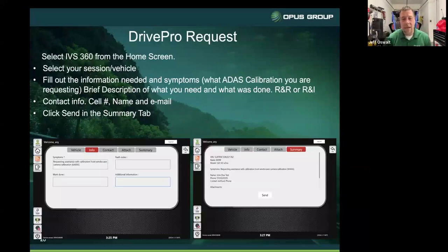If you are requesting it in the mechanical world on the Drive Pro request, now I don't use this every day, so I had to get a little help from my buddy Brandon Matthews. Many of you might know him. Select the IVS 360 on the home screen. To order this calibration, select your session and a vehicle. Fill out the information needed and symptoms. What calibration are you requesting? A brief description of what you need and what was done. Contact, cell phone information, name, phone number, all that stuff. Then click send in the summary tab. There's an example of that with the BMW, an X3 that he sent over to me. So that's how you will go about ordering calibrations through the mechanical team with Opus IVS.